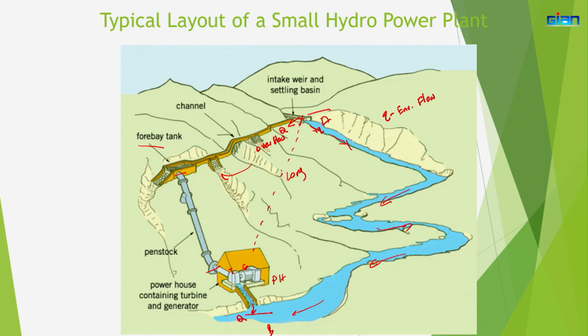So, we can see the other components of the power plant. In this course, we will see how to locate this location, why not here, why not upstream, right. So, we will see some ideas on that. When you have to identify them, then how many overflow canals we need, and what should be the slope of the canal, because if you use more slope, your head will be less. Therefore, typically the slope of a canal will be about 1 to 1000. So, that is 1 millimeter per 1 meter length, right, 1 millimeter, that is enough just for water to flow. We want just water to flow in the canal.